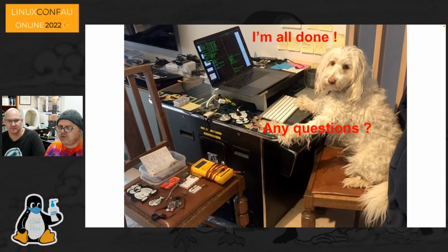One allows you to reference, let's say again, the ROM and the RAM of the RISC-V CPU is mapped onto the wishbone bus, and so when you compile the C code for the RISC-V, you can actually get the memory map of the various C variables, and so you can just look at those on the wishbone bus. You can see the C variable that's actually counting the frequency. So there's that way, and yes, we've seen that it's correctly counting the Theremin input.